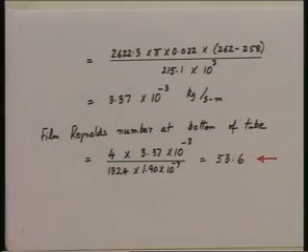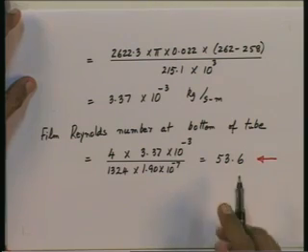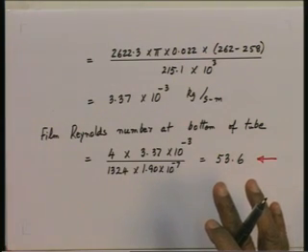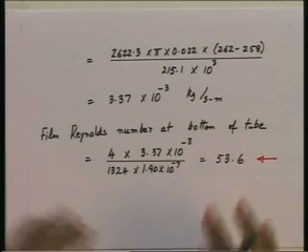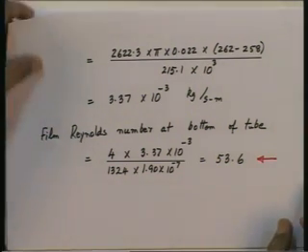Therefore, in the present case, this value 53.6 seems to indicate that perhaps the value of H bar which we have got, 2622, may be a slight underestimate. The actual value of H bar in this case for this tube may be about 10 or 15% higher. It is possible, because the film Reynolds number at the bottom is more than 30. 30 is considered a kind of dividing line. Up to 30, we get a very smooth interface. Above 30, one finds that ripples tend to form on the condensate film surface. So, this is one comment which you may want to note at the end.